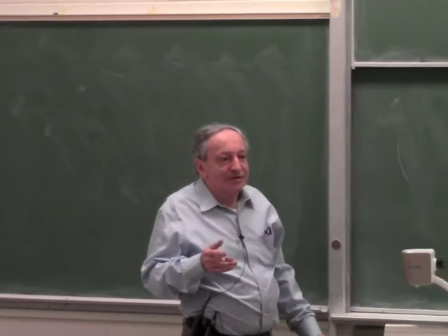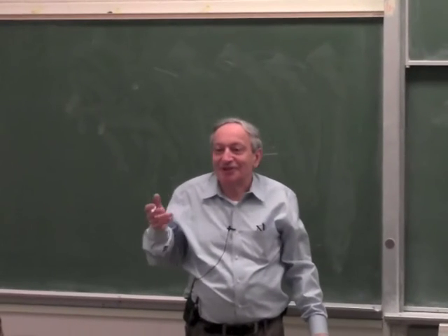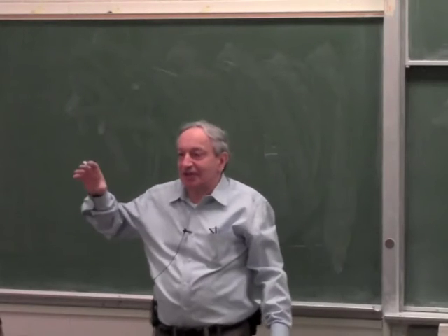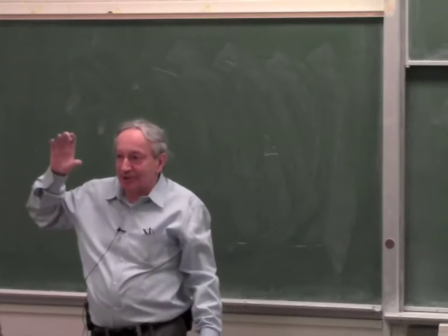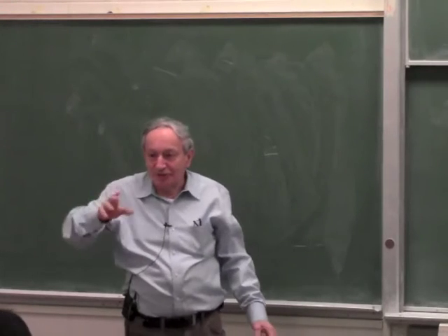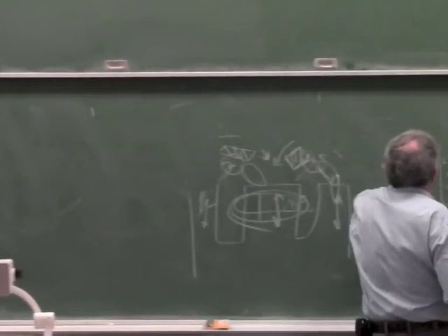How? Just switch the battery, because a PMDC motor is very simple: the magnetic field of the field is constant. It has N and S, which are by the permanent magnet. The armature, if you flip N and S, it's going to push instead of pull, and so on. So for a PMDC motor, you just switch the leads of the battery or the power supply.